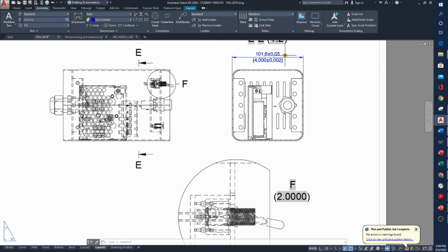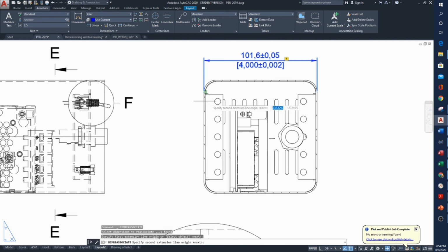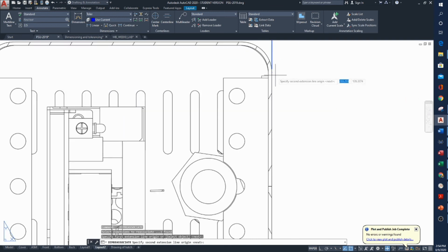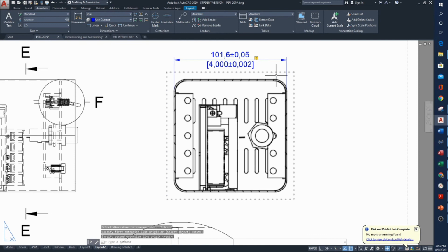The way to do that is to select the icon and reassociate it. And you'll notice this little X, and it's telling me what it's trying to associate. So in this case, I'm going to pick an endpoint. Endpoints are great because they are hard geometric features. Okay. In this case, I'll pick this other endpoint, and it should have fixed it.